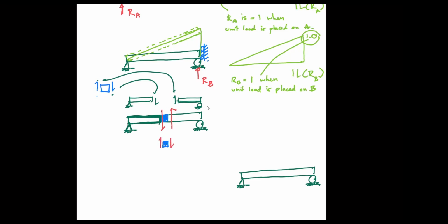So in order to maintain equilibrium, on the left is going up, so this goes down, back to this member. And because of the positive shear in the middle, on the right surface, it goes down, so this one goes up.